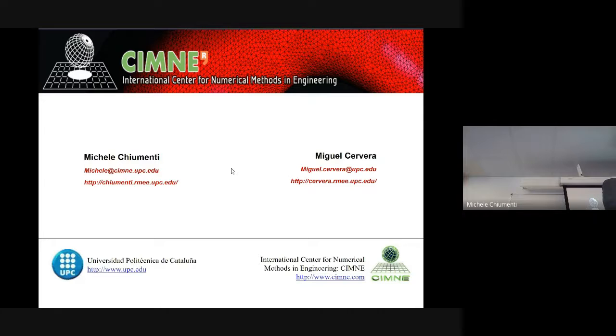According to our understanding, it is just a problem of what the element is able to catch in terms of strain and stresses. Because at the end of the day, you have a geometry. You have to discretize this geometry through finite elements. This finite element has some kind of kinematics. Each one of these has a different kinematics.